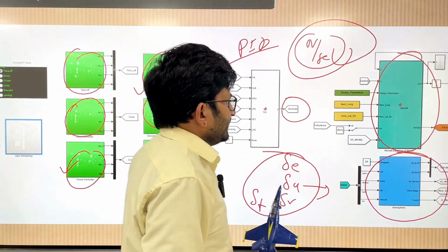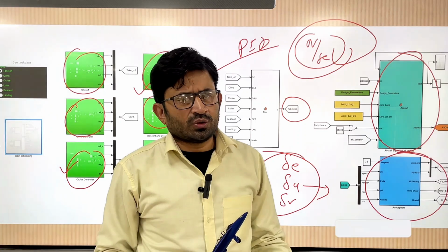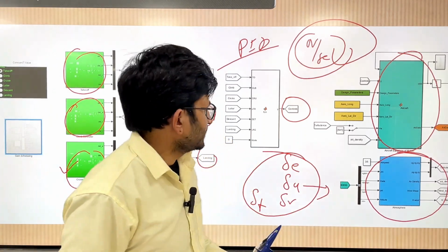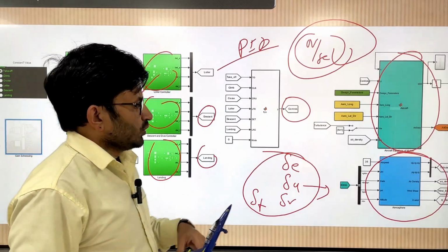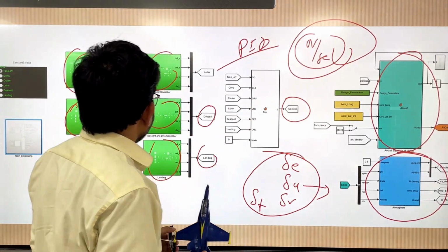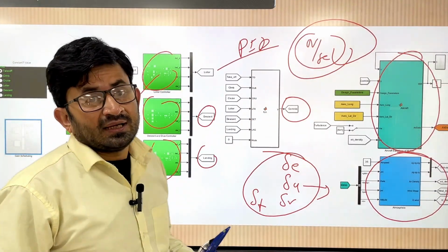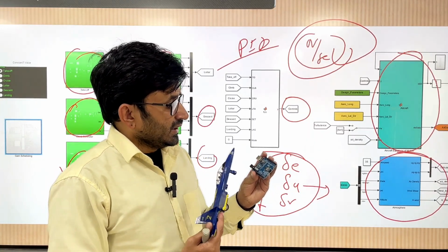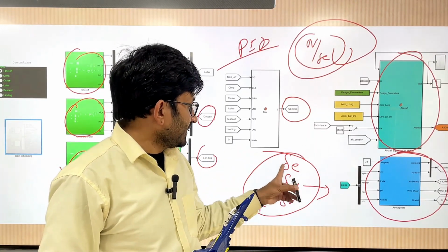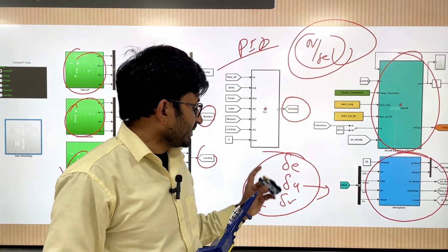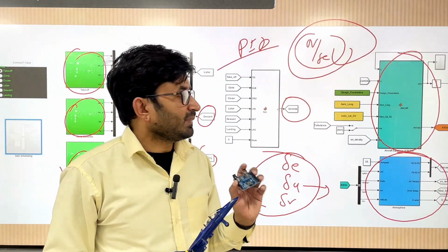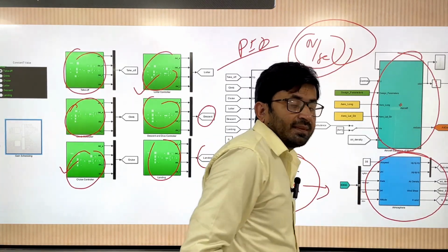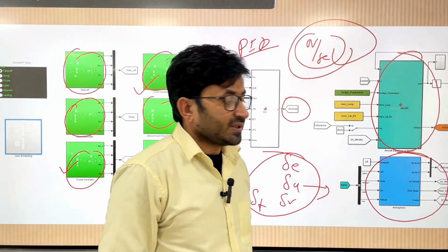And then once you deploy the code, for example in a microcontroller or Pixhawk, or in your own flight controller, then that becomes the HIL, because in this case you will give the commands delta a, delta e, delta r, delta t from the hardware, but the plant will still be sitting in the software. So that is called HIL.